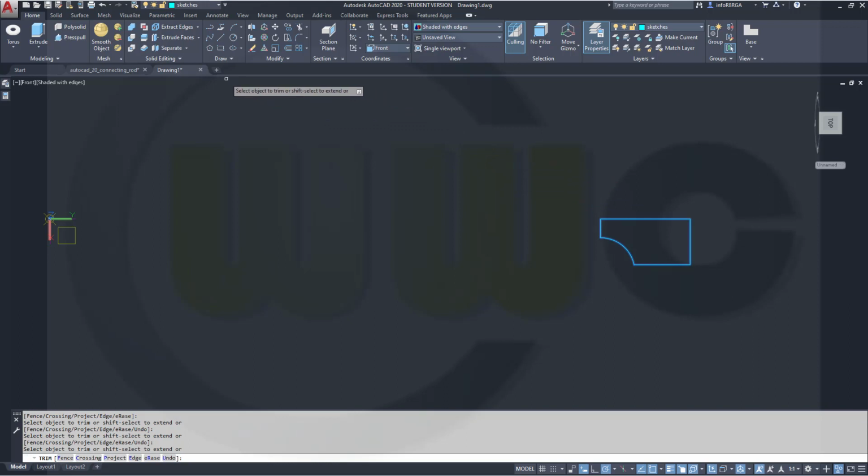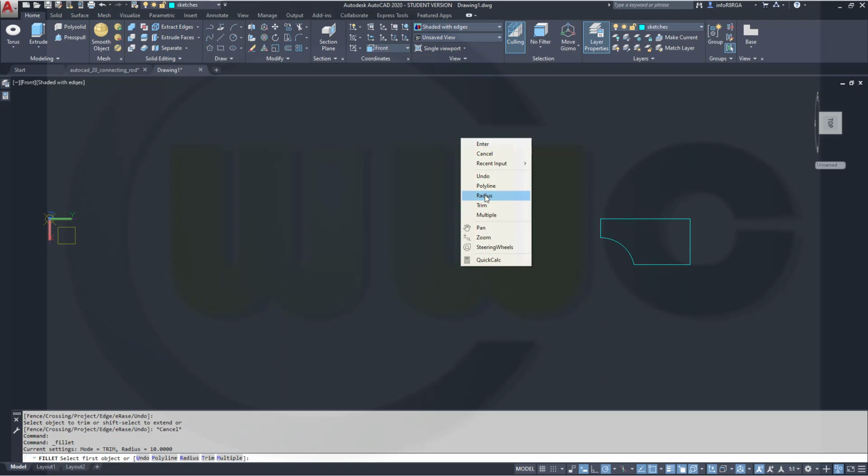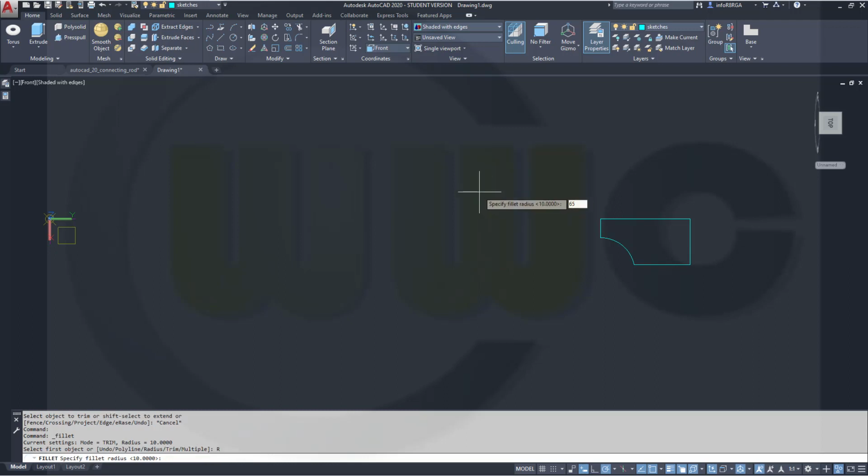And then I will need another fillet here, which is a radius of 65, and it should be between this one and that one, which does not work because it's a polyline, so I will have to use the explode command to make this work. Now I could do the fillet and the radius should be still 65. Yes, now I could make that fillet.